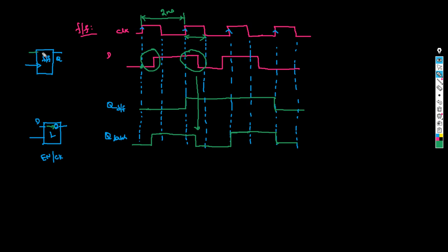In a flop, there is no D to Q direct path. There is no path D to Q. It is always clock to Q, based on the clock edge only. We'll talk about something called a timing arc in the upcoming classes. So positive latch means during this positive phase, it exactly copies over here, and during the negative phase it just retains its state. Here the data is changing, but it is retained. Here also the data is changing, but it is retained.